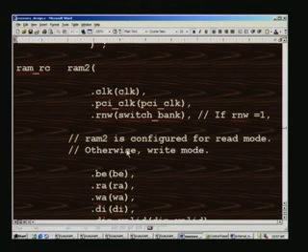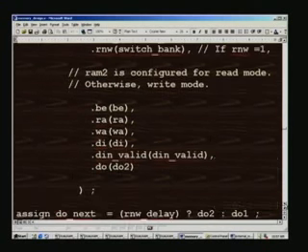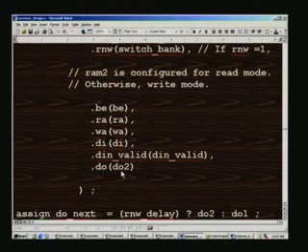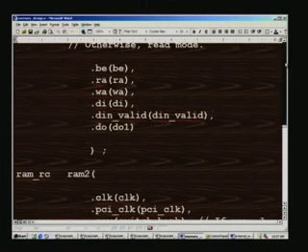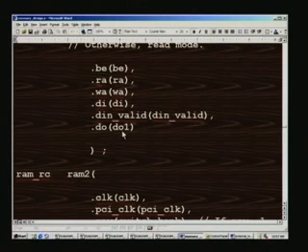versa, and that is how you can continuously fire the image into this dual RAM, and automatically this swapping will take place. This R and W will be automatically taken care of in a controller which we will consider when we consider the DCTQ design. That controller is not part of this dual RAM. And once again all the other signals are precisely the same, except for the fact that DO is nomenclature now. This DO2 refers to this top design, that is the dual RAM, and similarly for the RAM 1 it was nomenclature as DO1. So this distinguishes, that is why this has been declared as a wire,